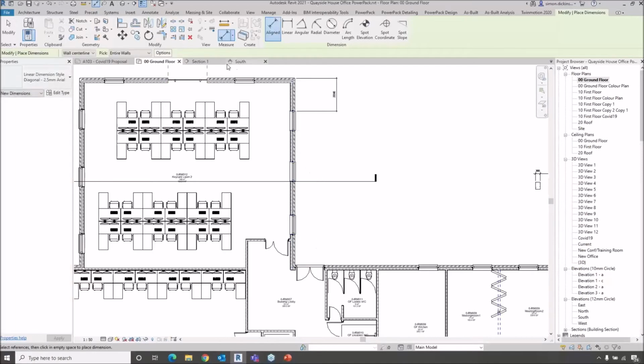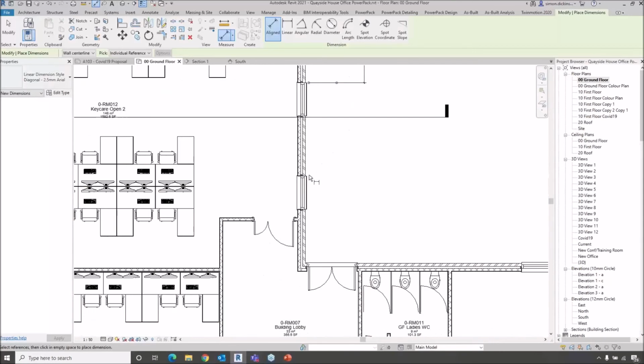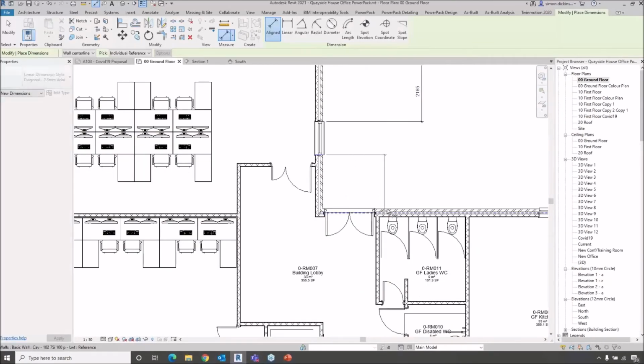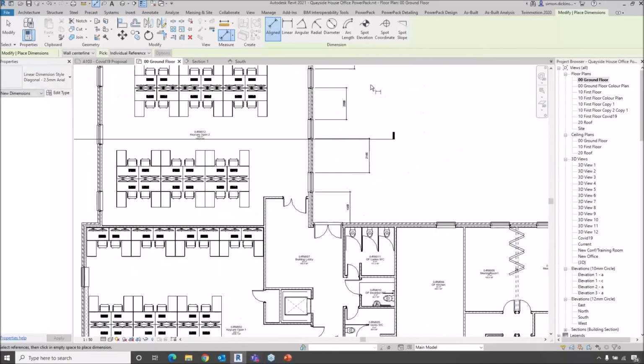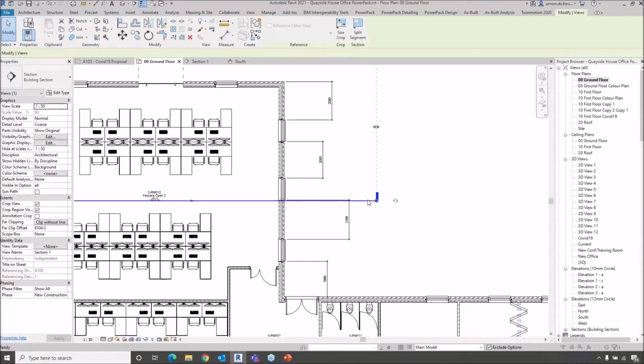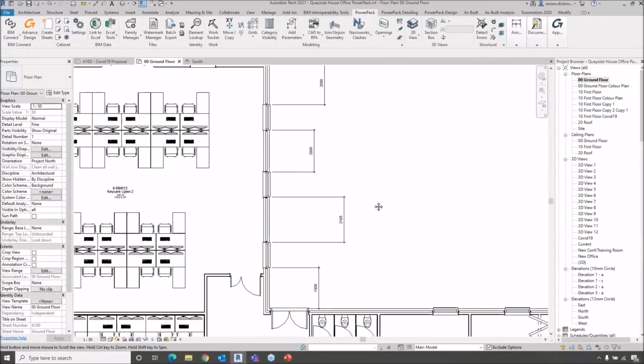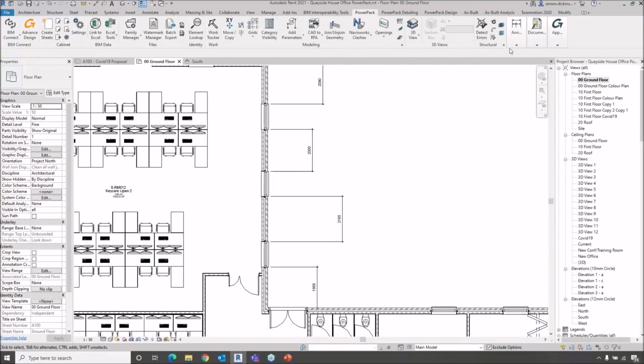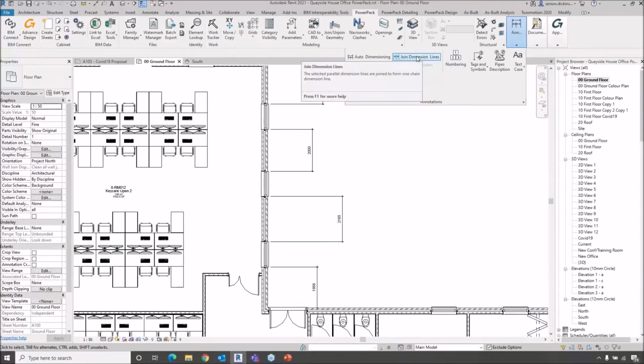Oh, it's gone back to entire wall. Didn't want that, so let's put another one in that wall section, stick it there. Let's dimension this wall section, put it there, and we'll just dimension that one and put it there. Okay, so I've now got these 4 dimensions all looking incredibly untidy. Let's delete that section. Okay, so what we can do with the final tool in there, which is this join dimension, yeah, is I want to join all the dimensions together.